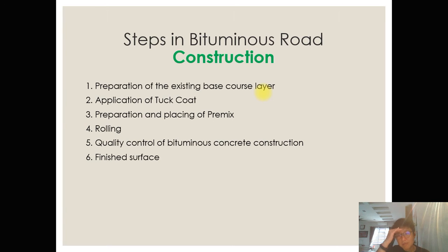One of the problems that we encounter when we have flexible pavements that don't quite last is that the way we construct is not quite correct, especially in terms of compaction. All right. If you recall, when we did soil mechanics, we talked about compaction as well. If you do not compact your loose material into the densest form possible, then you cannot expect it to last, right? When you load it, and you have rainwater coming in, water plus soil is never a good thing.